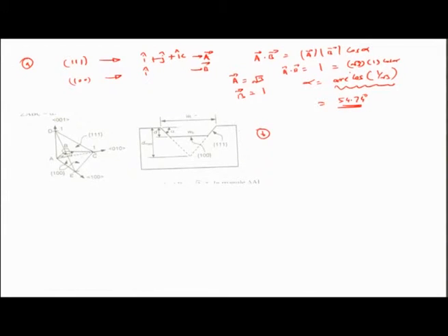Part B of the problem mentions a total channel width to start with of 100 microns and a vertical etch rate of about 1 micron a minute. Let's call this etch rate 1 micron per minute. So if we figure out the relationship between WB and WT, obviously WB would be represented as WT minus twice whatever distance d is covered within the number of minutes that the etch is allowed to continue.